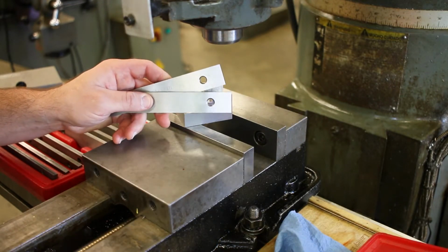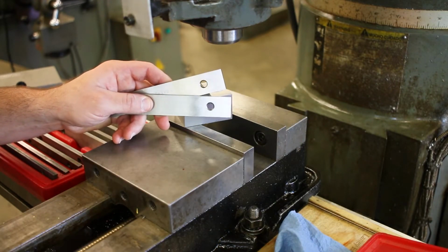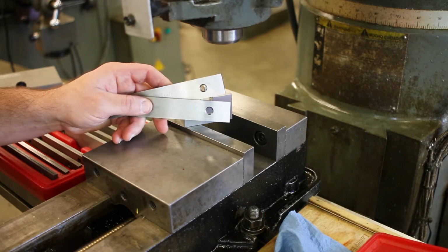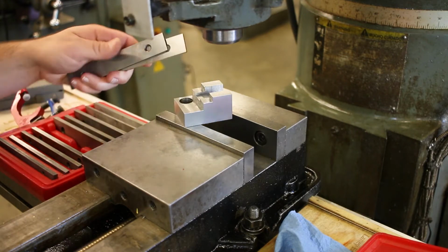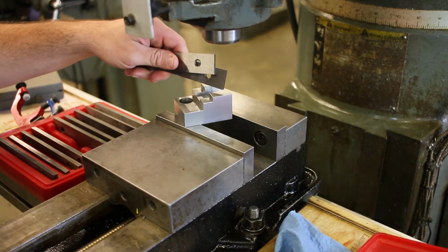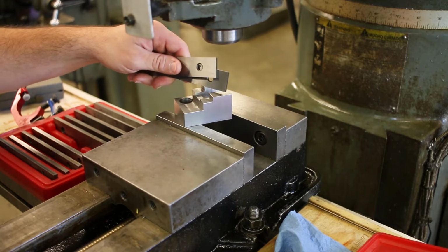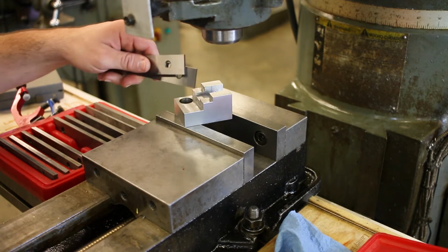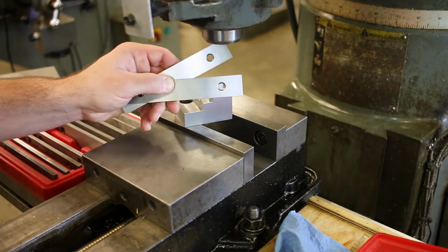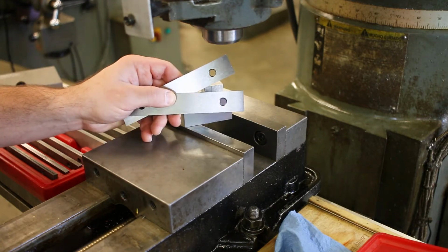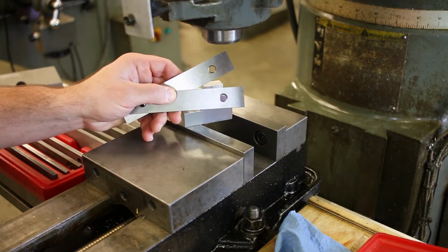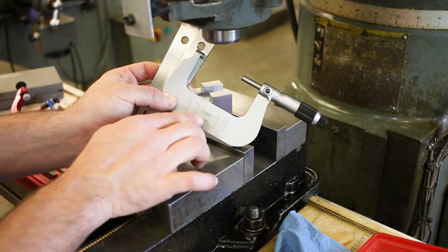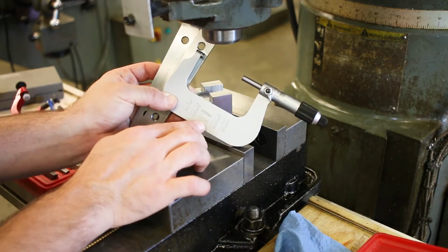When you're selecting the size of your parallels, remember that there are sort of 2 things that you're looking out for. One is that you want to be able to hold as much of the part as you can while still having access to all of the surfaces that you need to machine. The second thing is that you need to allow for clearance for your precision measuring instruments. The largest distance that we have to measure on this part is going to require a 2 to 3 inch micrometer.